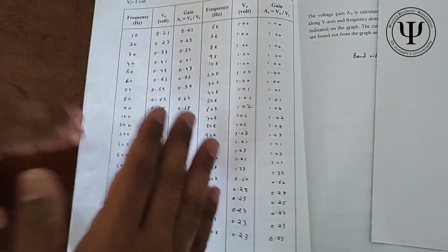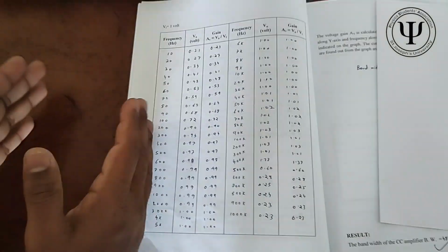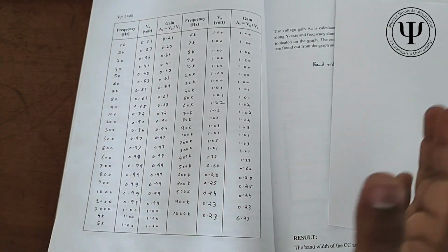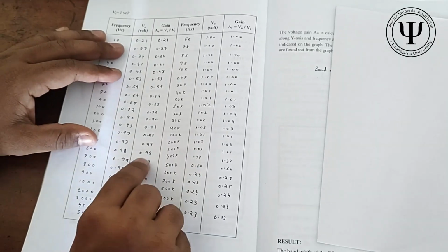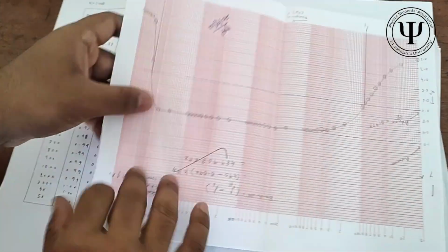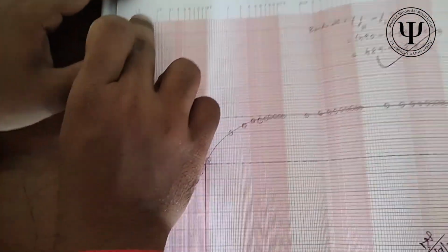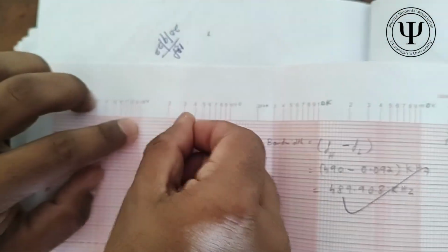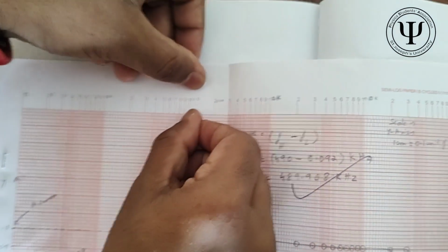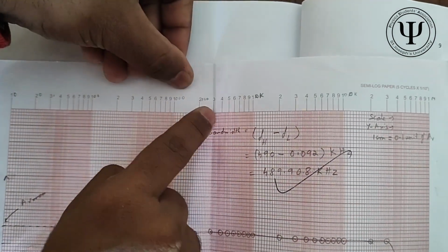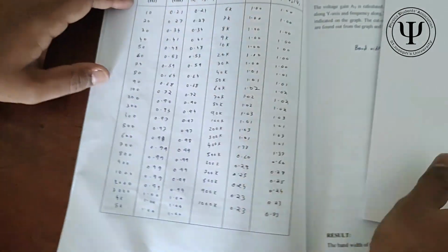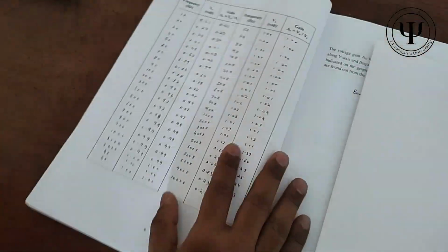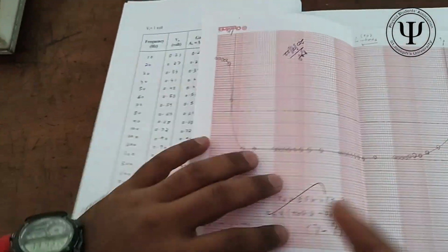Why do you do this? If you take a normal graph and plot this, you know that 10 to 1000 kilohertz will be a really big graph. Since most of the values for us are literally constant, we can use a log graph. This first 0, 1, 2, 3, that is your tens. From here, it becomes 100, 200, 300, 400, 500. It becomes 1000. Then 1000, 2000, 3000, 4000. Given the nature of the values, you can use a log graph. Okay. So now you took the values and plotted them on the log graph.